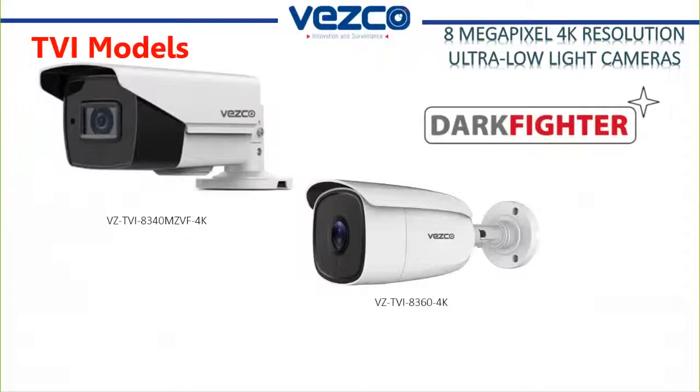Our TVI models are also 8 megapixel 4K resolution, but they have an advantage. They all have ultra light sensors. The chipset of this camera is Dark Fighter, very similar to a Starlight chipset. So these cameras can work with 0.0001 lux. We have 2 models. One is a varifocal motorized zoom with 40 meters IR.